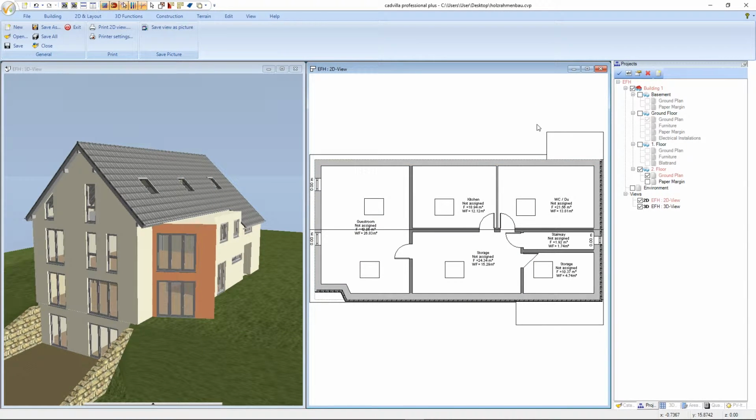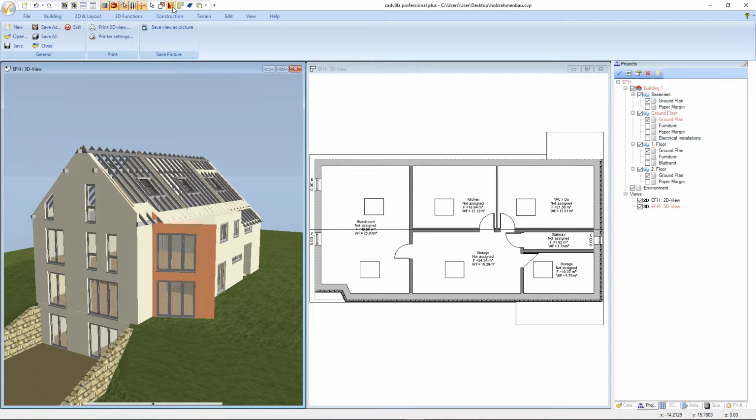The timber construction is now deselected for all affected walls in the second floor. In the next step we will select again the 3D view and we deselect the cladding. We make a right mouse click and we select Visibility.